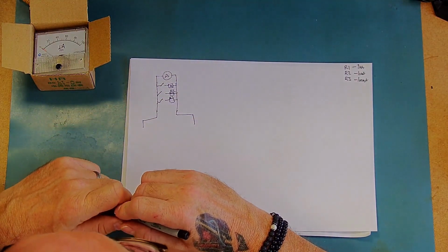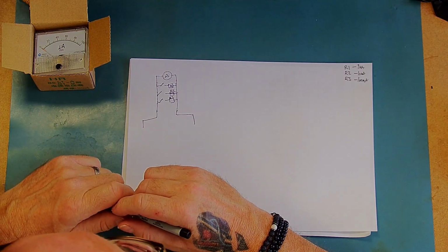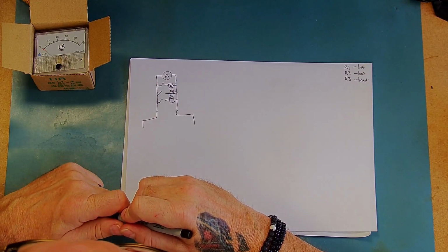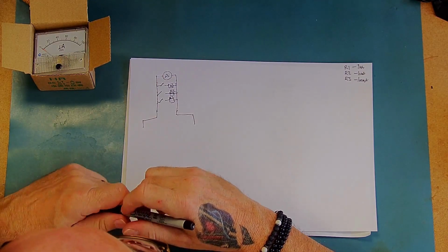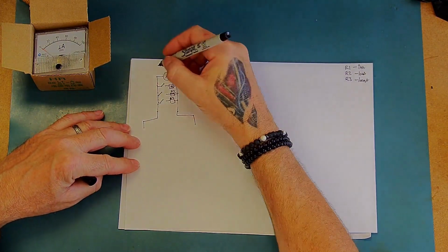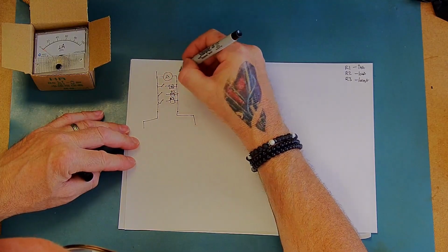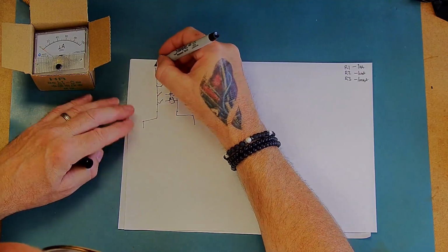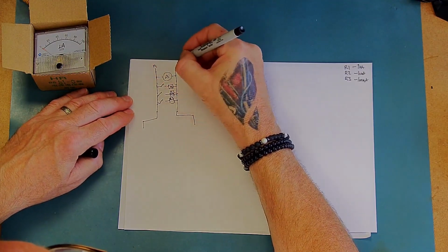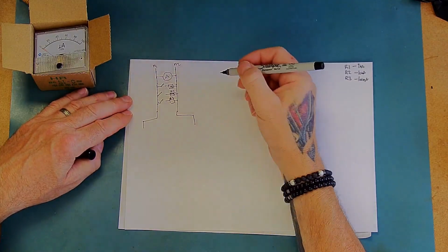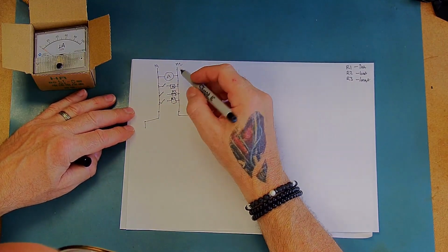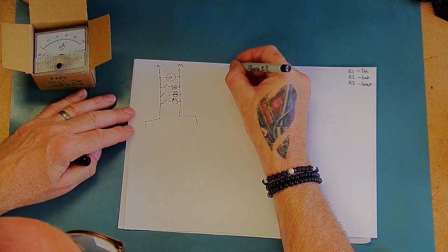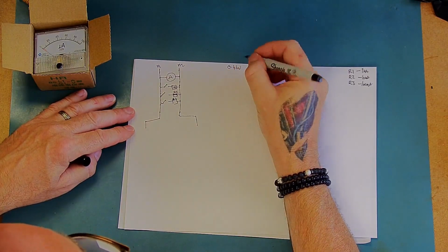Well, I've had a bit of a think about it and I've come up with a couple of ideas, and I think the most promising one is the one I'm going to try first, and hopefully that will actually work. Obviously I need to measure across the actual ammeter itself, so I'm going to have a couple of measurement points. I'm going to call these M1 and M2. Now obviously we know that for full scale deflection of this meter we have 0.46 volts or thereabouts.